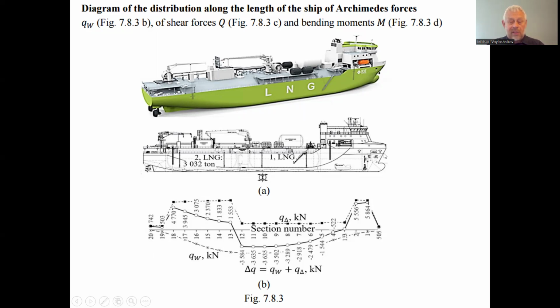So the danger is another one: when the ship moves with the trim to the aft, there perhaps could be slamming of the bottom in the board part on the surface of water, if the ship has trim to the aft due to uneven distribution of the cargo, the absence of the cargo in the first capacity, but only availability of the cargo in the second one.